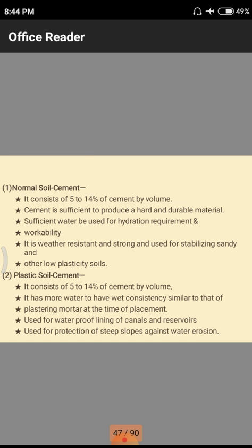There will be no water on the top layers. To arrest those penetration techniques, simply we have to give some soil cement lining to the canals and reservoirs. Then they will store the water for a long period of time.